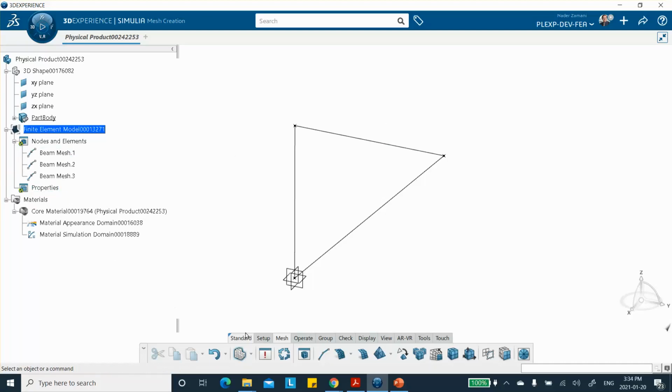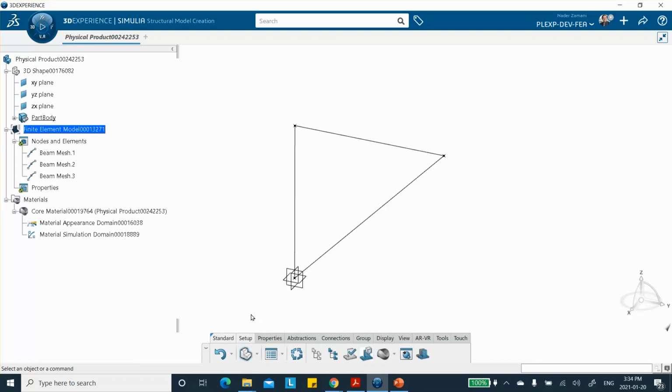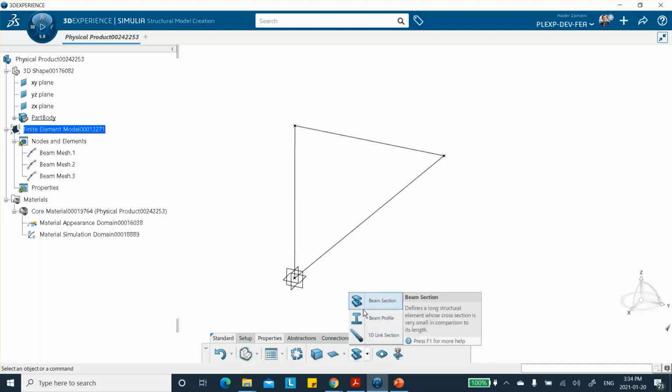And then the properties. For properties, you have to go to, let's see now, to model. Here, we don't want mesh. We go to model right there. See that? Model. And under properties, we want this beam section, but we really don't want beam. This is a truss, so they're not beam elements. In reality, this is a link property.